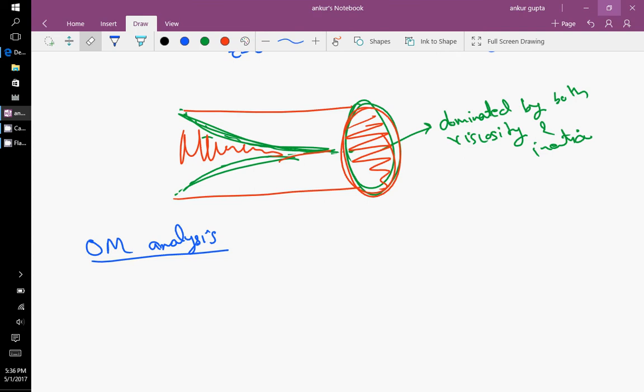equation. So for the equation of continuity and Navier-Stokes equation, we can also make some assumptions. So let's also write our assumptions. We can assume the flow to be steady, right? That's a reasonable assumption, that the flow will be steady. So we can drop off the time term, and we can make rho and mu constant.